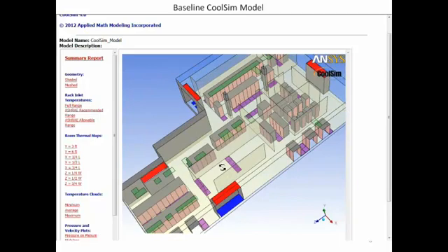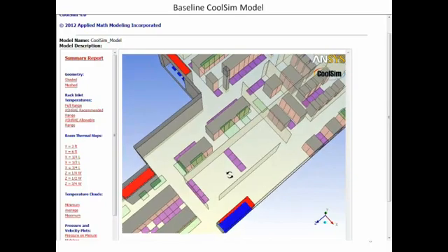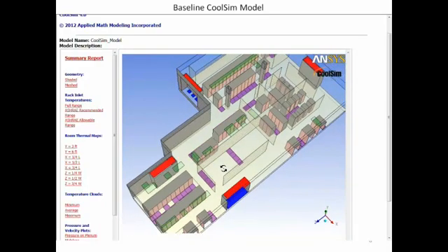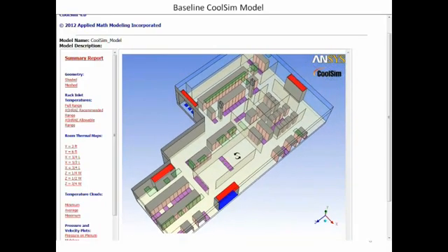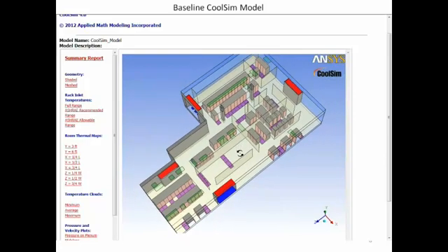You will also notice, however, that some rooms have nothing in them at all, like this one right here is empty. So the point is that you buy the cooling capacity, in this case we've got 4 cooling units, to handle worst-case, max load conditions, and you slowly, over time, come up to that load condition. And what you need to try to do is scale your cooling to match your IT load. Now that's the trick, is try to get the cooling to be consistent in terms of its capacity with the total IT load.